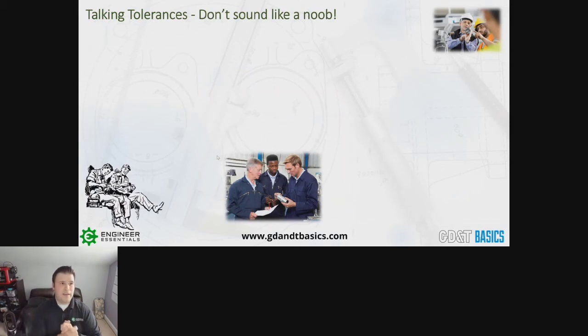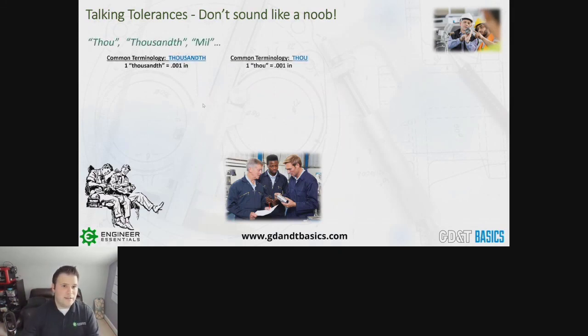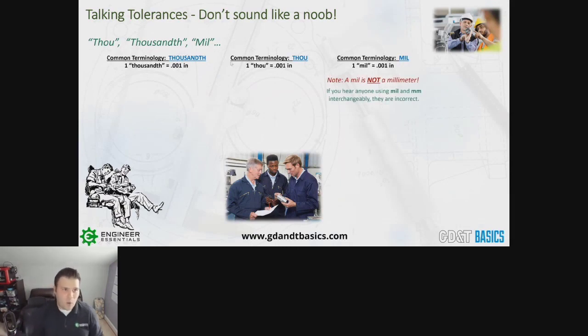Again, one quick thing here that I wanted to get into to make sure that you don't sound like a newbie when you're talking tolerances, especially with production and quality, is the shop talk, let's call it. For those of you who are not aware, the word thou or thousandth or mil, all of those mean 0.001 inches. Someone says that's a thousandth. They don't mean a thousandth of a millimeter. They don't mean a thousandth of some other unit. They mean a thousandth of an inch.